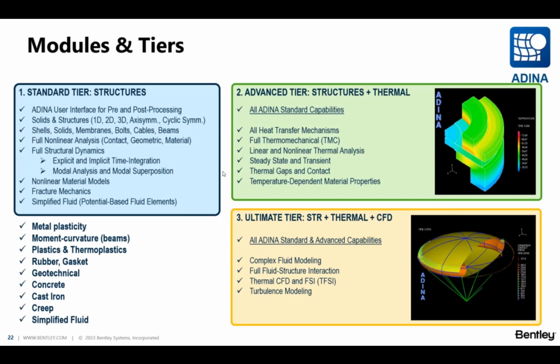And I wanted to bring your attention to the bottom of that list. It says simplified fluids, the potential-based fluid elements that I will be presenting in a moment, which are different to the computational fluid dynamics, the CFD that you see at the bottom right of the screen. So these are fluid elements available within the structures module, and we will see how they are useful to model, for instance, liquid-filled tanks subject to earthquake excitations or dams and reservoirs, and so on. We will get there in a moment.